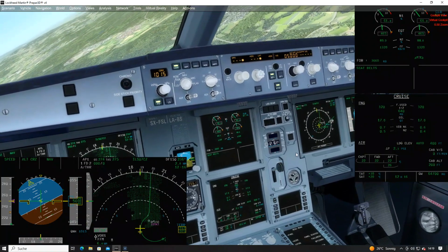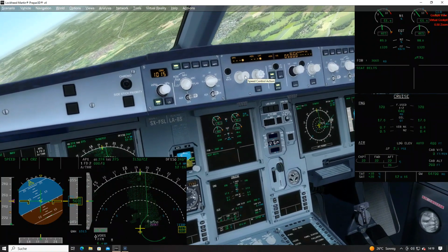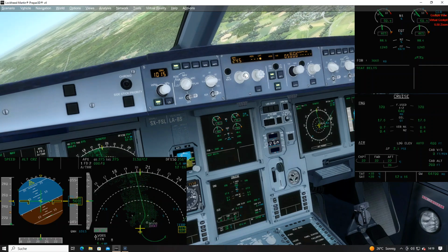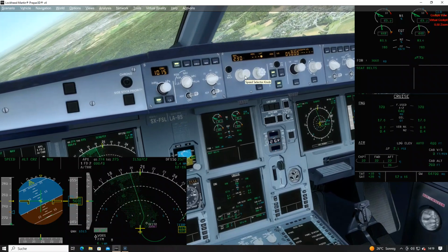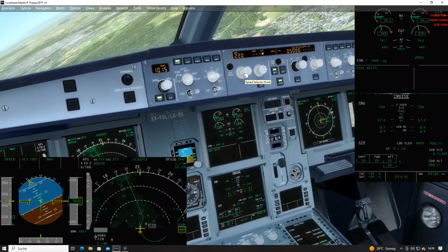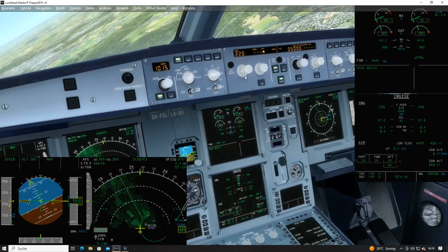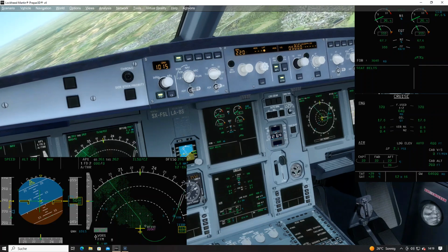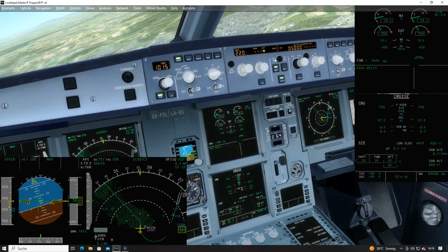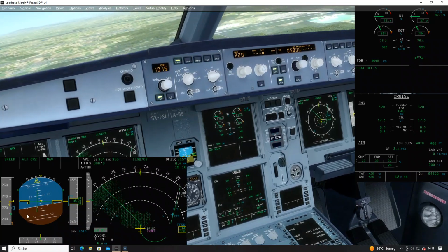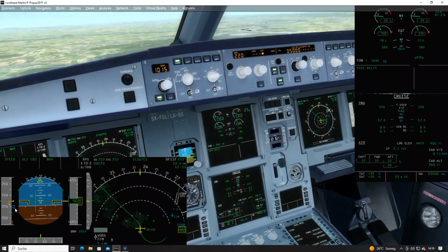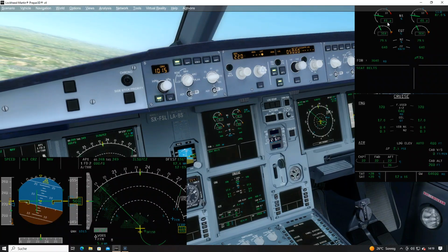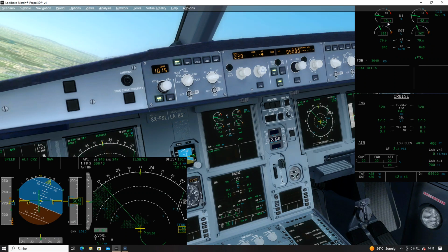The pilot can act, so if something goes beyond expectation or not as intended, I can pull and have a selected speed of 220 knots as required by the procedure. So if there's automation doing something wrong, for whatever reason it is, there is an obligation for the pilot to act. Thrust is reduced, aircraft is decelerating towards 220 knots. And reaching 220 knots, we have a thrust increase to maintain 220 knots.